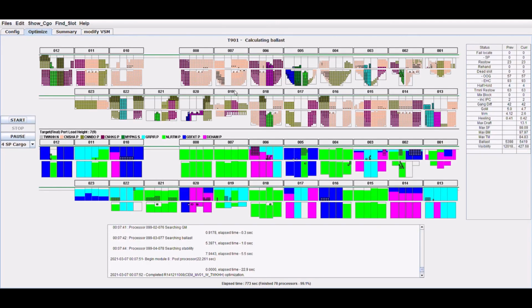In the next session, we will continue to make the stowage plan from Shanghai using the stowage plan of the previous port created by the engine as the input of the inbound bay plan for the optimization run. We will repeat these optimizations until the final port, Port Kelang, and will make sure whether cargoes are loaded and ship stability are satisfied. Thank you.